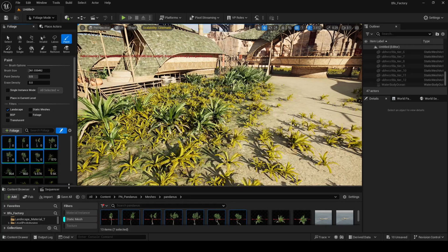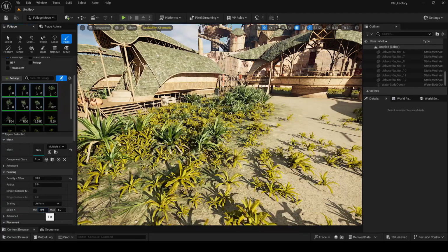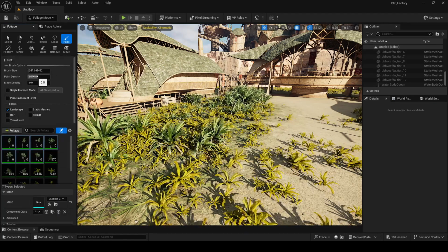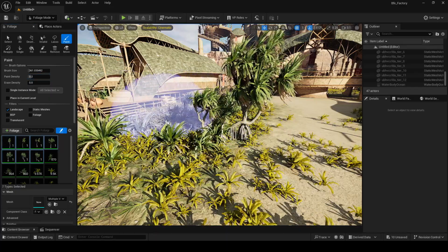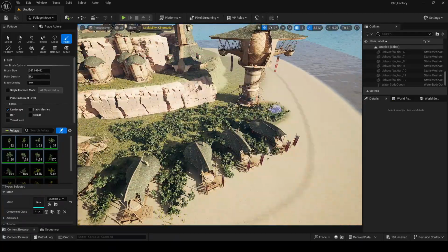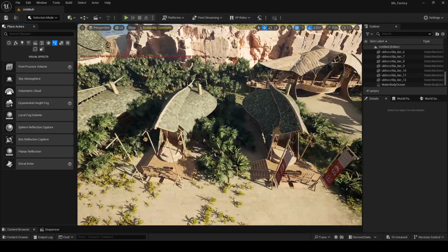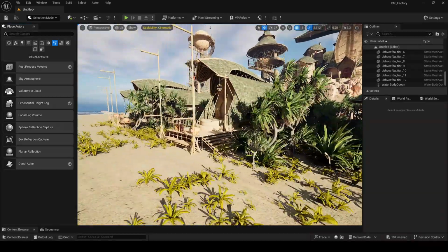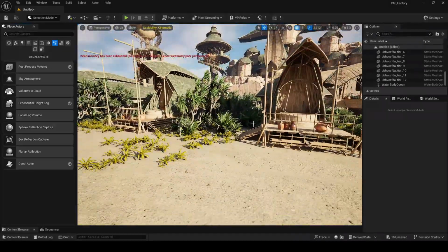Select this all and let's change our density 0.1 and 1.5, sorry, 0.5, 1.5, it will be better, and the density will be 0.2, and let's apply. Yeah, that's good. Let's brush it, again only in the grass layer. You can see this is looking fantastic now. Now you can see there are 3 different layers: small grasses, medium grasses, and some plants here.